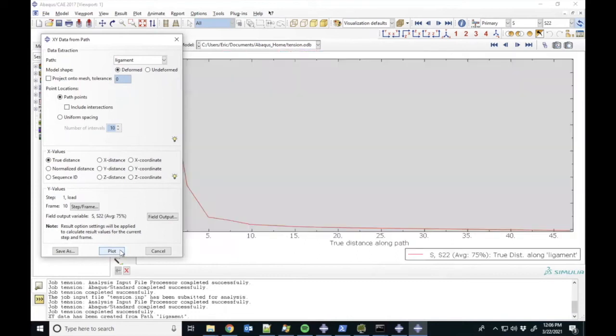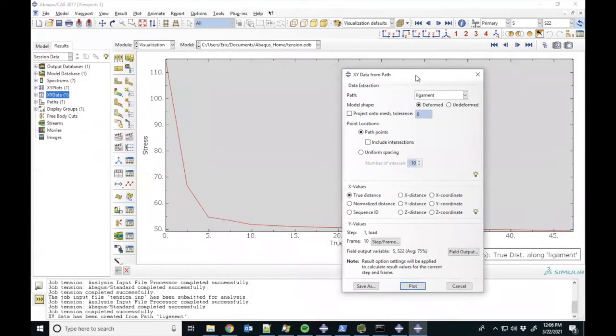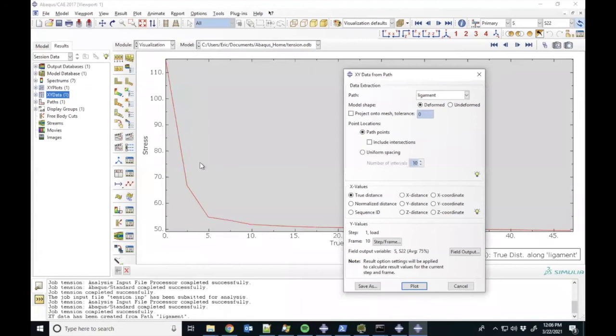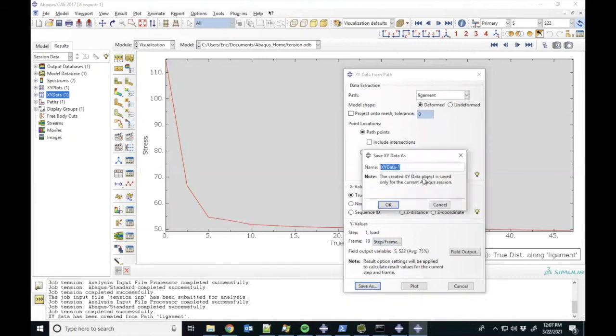If you click the plot button, you can see a preview of the actual data output that we're going to get from this process. On the y-axis, you have the stress in megapascals, which you can already tell is taking on its peak value of around 112, 115 megapascals, severely under-predicting the theoretical result of 150 megapascals. But to get better clarity on how this compares with the analytical solution, we're going to export these data into MATLAB and co-plot them with the analytical solution, which will give us a lot of insight into how changing our mesh can improve our approximation of the analytical solution.